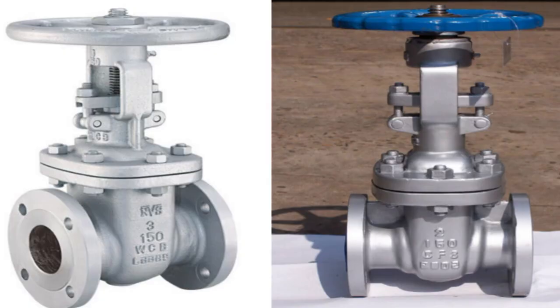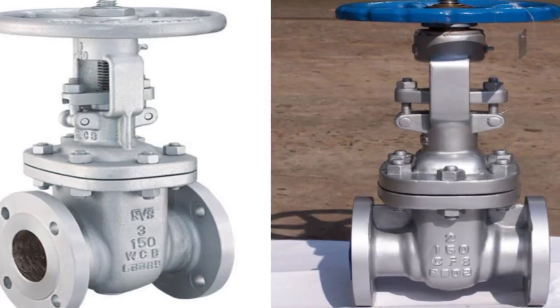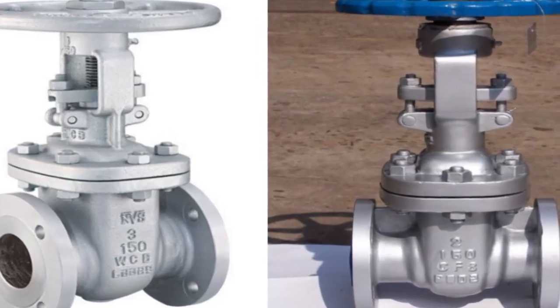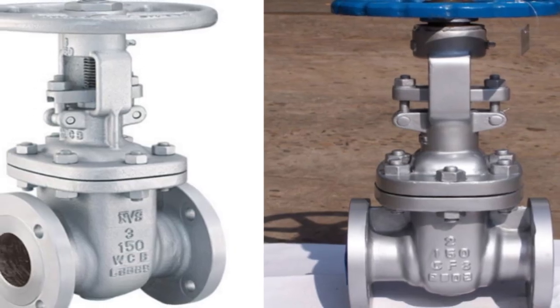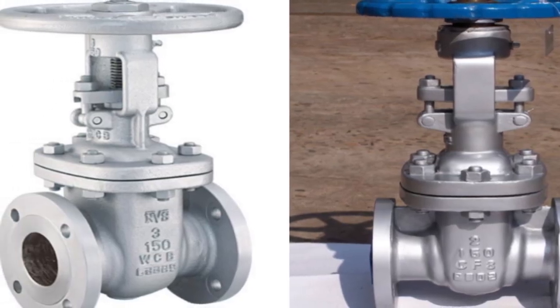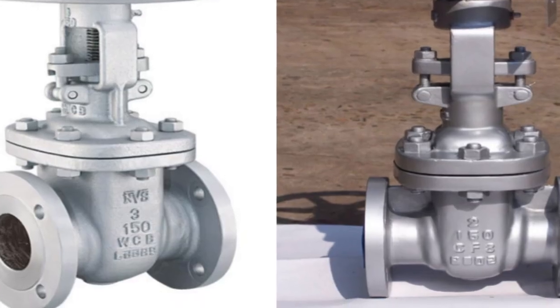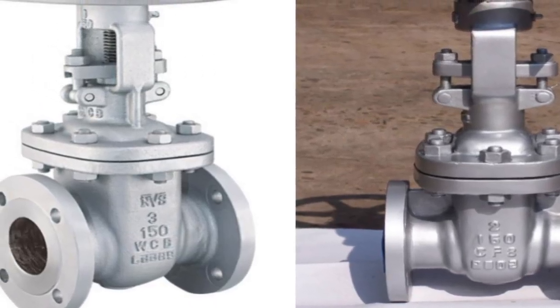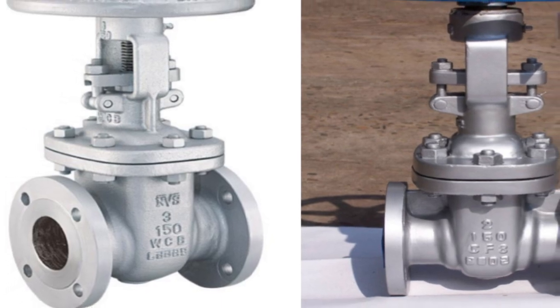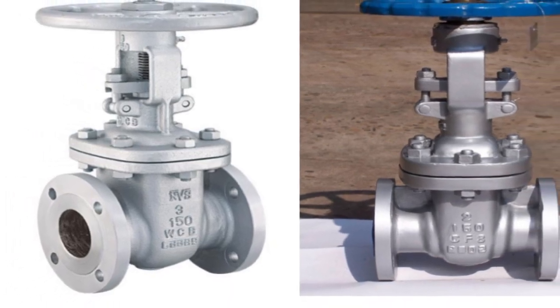Gate valve. A gate valve has a round body with a flat metal gate inside. On top, it usually has a round wheel handle. When you turn the handle, the gate moves up to open the flow or down to stop it. The inside pathway is straight, so when the valve is open, fluid passes easily with almost no resistance.